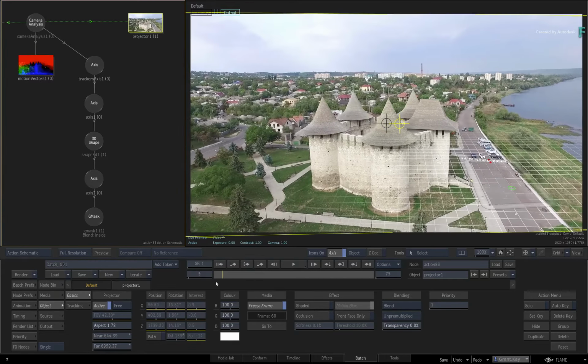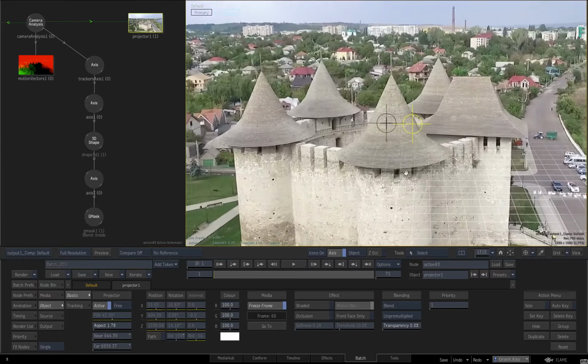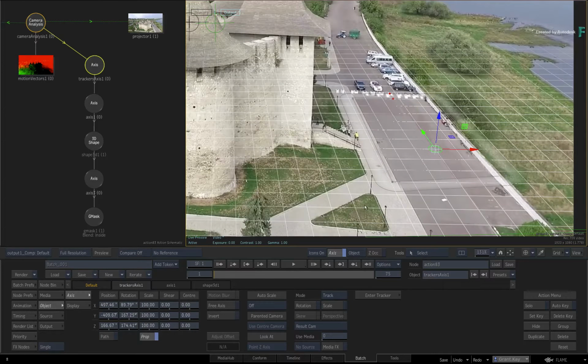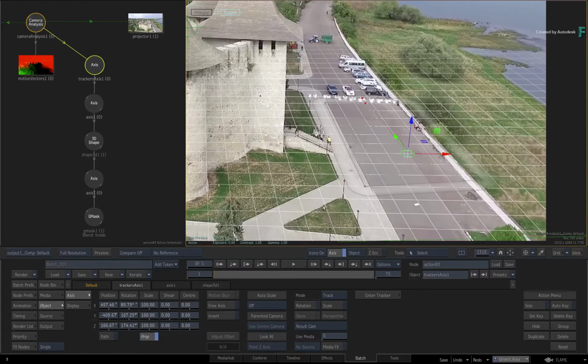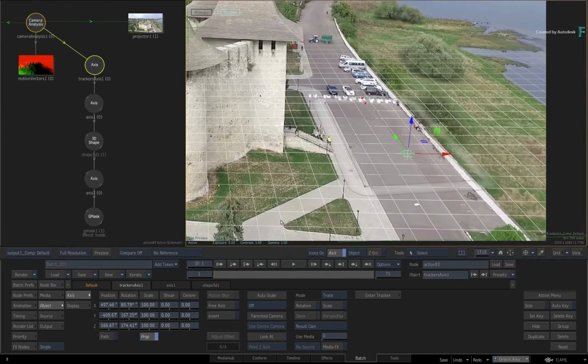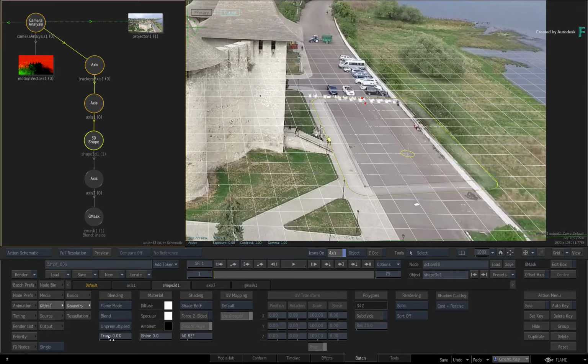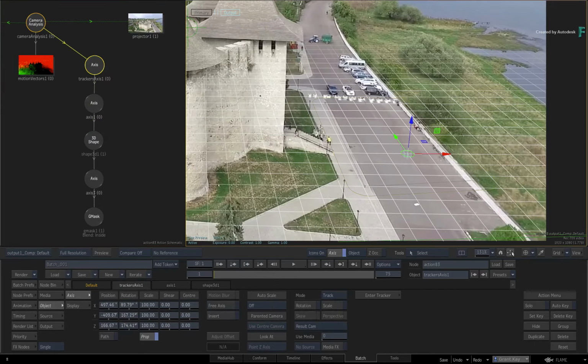Finally, if you did use the optional steps to blend the 3D shape with the background, you will get a white halo along the softness gradient. This is the white of the 3D shape mixing with the projection. To remove this halo, go to the 3D Shape's Geometry menu and make the 3D shape totally transparent. Transparent 3D objects can still receive projections.